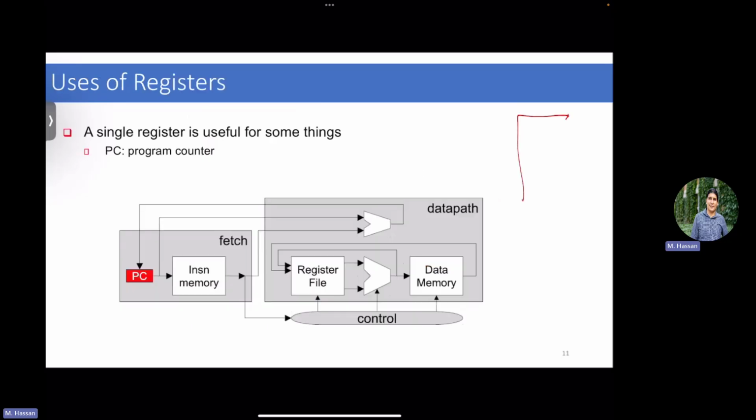So our logical view will be, well, I have a write port, which is data basically. I have a read port 1 and read port 2, which are also data. I have an address. And then I have a write enable simply. And because this is a register, you also have a clock, right? Because we overlook this, you can also have a reset and these types of things.